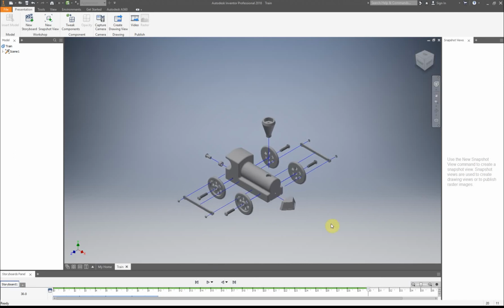Okay, so right now I have my entire presentation view all set up, or exploded view, depending on what documentation you're looking at. And everything is individual, so if we wanted to, we can count every individual piece very easily. So the next thing I'm going to go over is this snapshot views, because if you saved in the middle, it'll save a snapshot view.